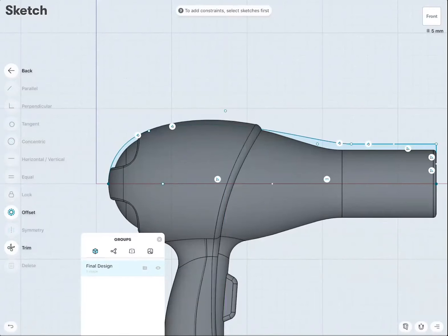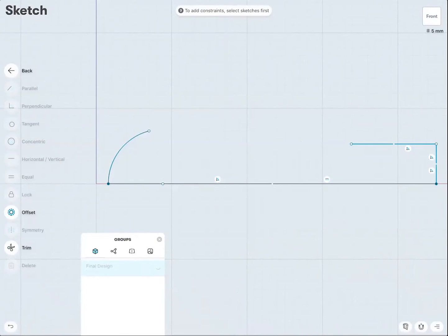I find actually here we have 1, 2, 3, 4 points. That might not be enough. I need one more extra point. So sometimes you will see what you start guessing with is not enough. So we have to create a new curve. So from here again, 1 for the tangent, 1 for more the profile, another 1 for the tangent, and then we stop this one.